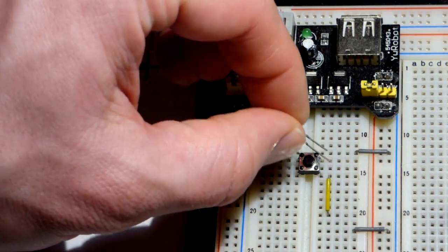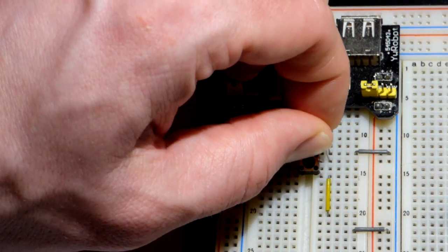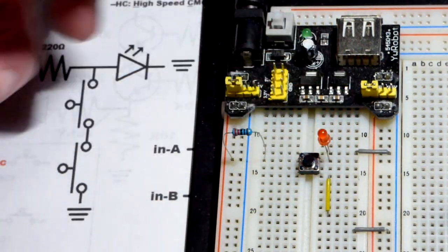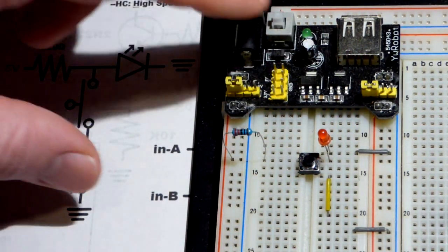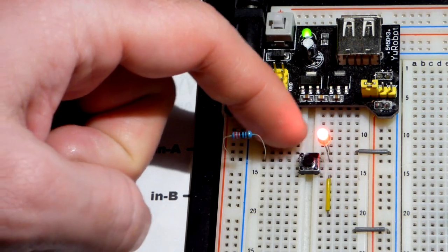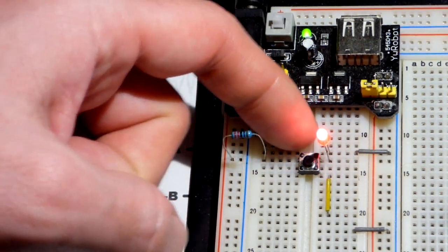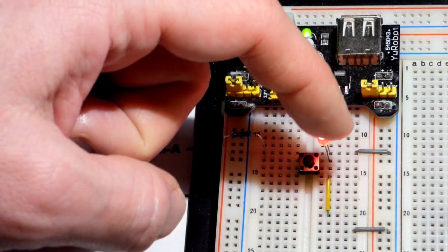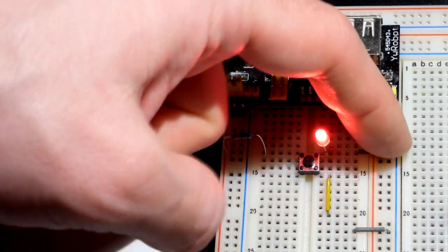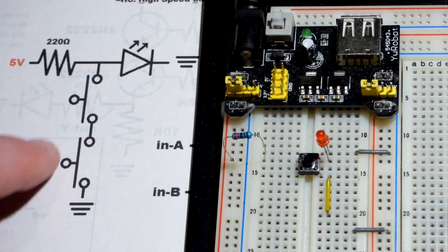So you should probably already know that by now if you're learning about NAND gates, but I thought I would cover it again. So right now we have a situation where the LED is normally going to be on. We got current going through the resistor and then across the switch, because these 2 pins are always connected to the long lead, the anode of the LED. The short lead, the cathode, goes directly to ground. So now we're going to build up the NAND part of it. So we need 2 inputs for this NAND.